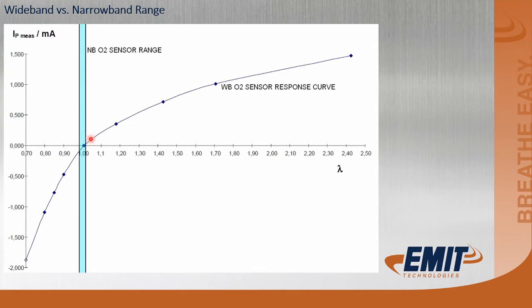Again, it does not measure oxygen, but rather the amount of oxygen needed to consume any remaining combustibles in the exhaust. So it's the same as a small catalyst. Very, very small window. Again, anything outside of this window, a three-way catalyst is not working. But you can see the range on a wideband O2 sensor is much greater and much more linear.